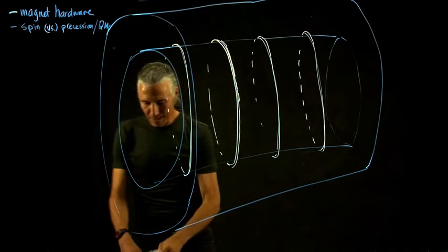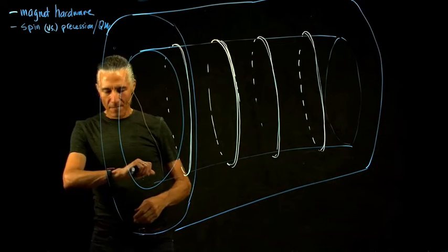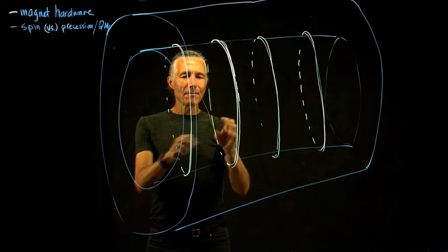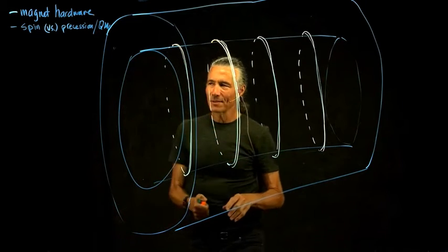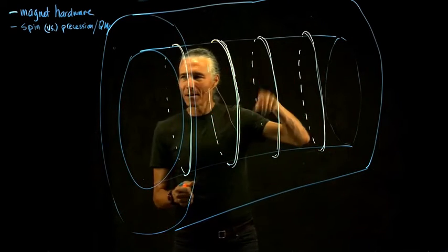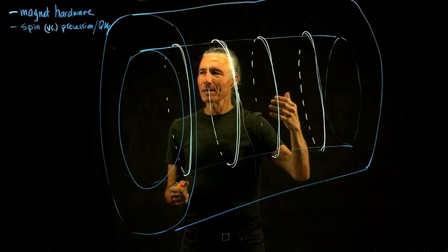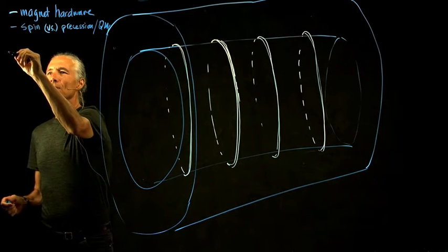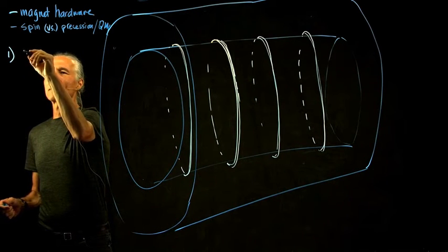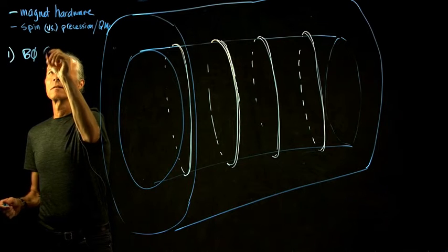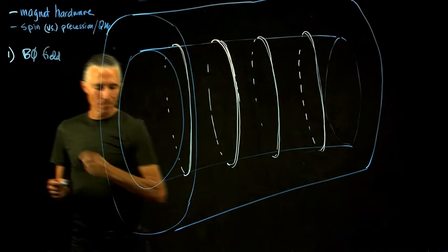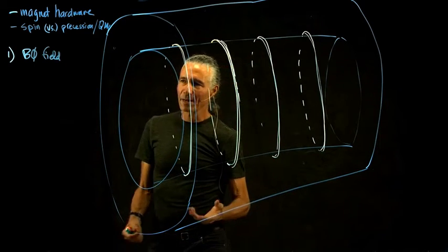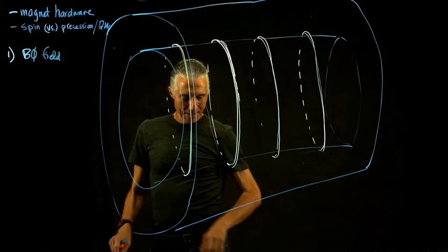That's what makes it quite dangerous, because if the power goes off and the lights go off and every single LED on the magnet is off, it's still on. The current's just going around and around by itself, making this huge magnetic field. That huge magnetic field is the first piece. That's called the B0 field. It's a strong field. Ours is a 3 Tesla, a 2.9 Tesla field.